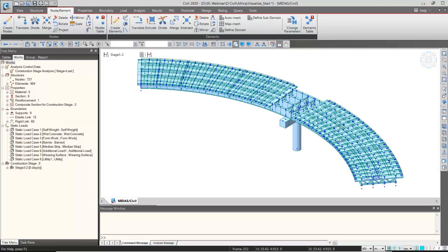The wet concrete load which was there instead of these deck elements is also removed. So you can see over here there is no plus sign. That means nothing is applied. And then we have the next stage, the third stage, wherein the wet concrete for the support is applied. And after that we have 3-4 wherein the deck is now hardened at the support location as well. So that's the next stage, and then we have the stage 4, actually, not the last.